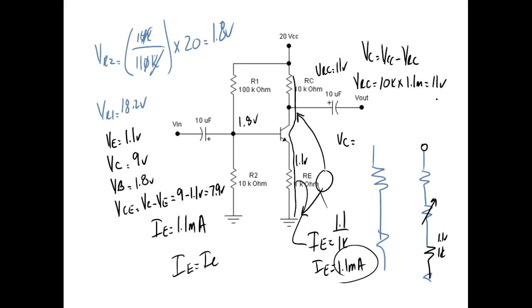Now this resistor comes into play, but this resistor is seen as a huge guy, and we'll look at why in a minute. If this has a beta of 100, this 1K is seen as 100K. And what's 100K in parallel with 10K? Well, it's about 9.9K, so basically we can ignore it. This resistor right here is seen as times the beta of the circuit, and we'll look and see why. So let's bring an input signal into this thing and see what it'll do. We've got to bring a very, very small input signal.